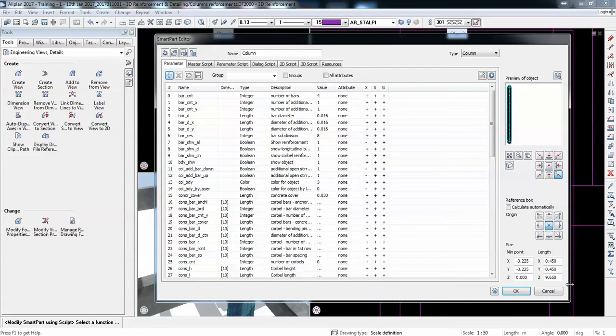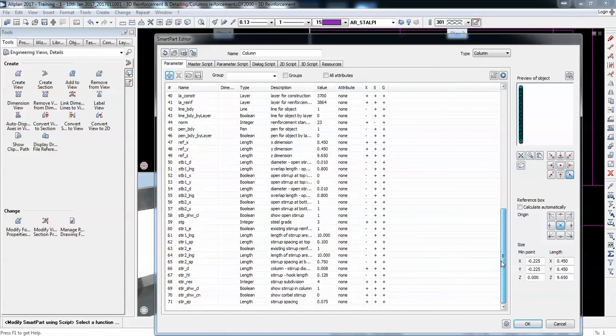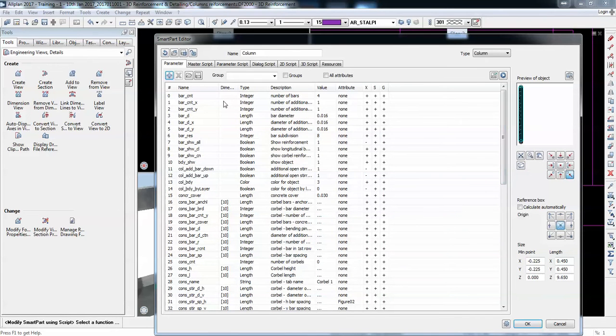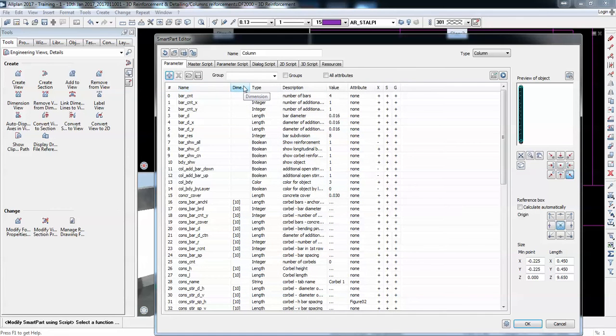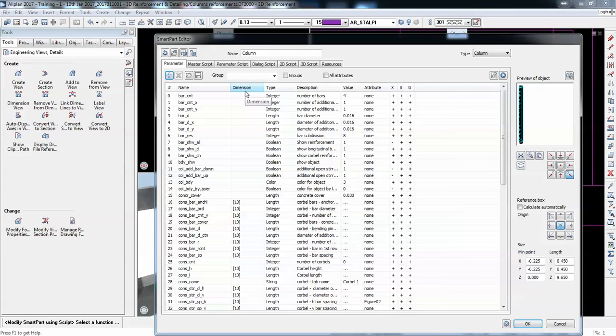Okay, so I've sent you also a tutorial on smart parts, but I don't think it's that relevant. It teaches you how to make a parametric table, but I don't think you need a table with chairs and everything. So how this works, you have to define parameters, which can be anything you like to change. So any parameter, both dependent or independent. So you can also get parameters that are dependent on other values, not necessarily the parameters that will be inputted by the user. So from the scripting smart parts point of view, you have to be a developer. You're building a smart part that other engineers will use.